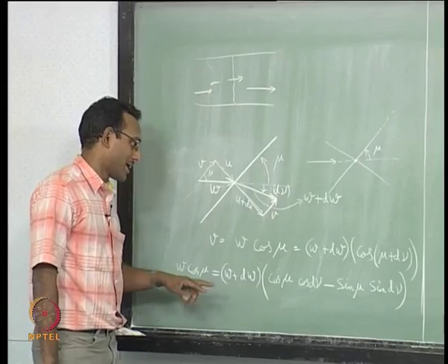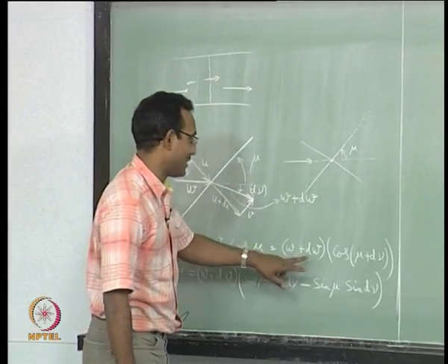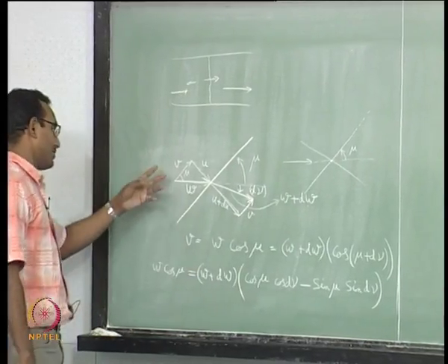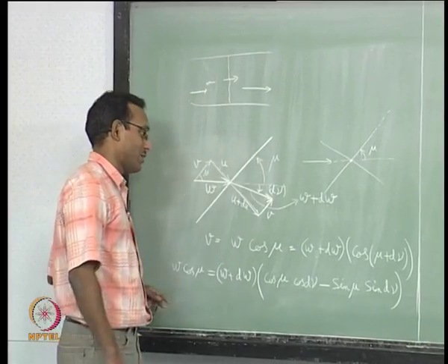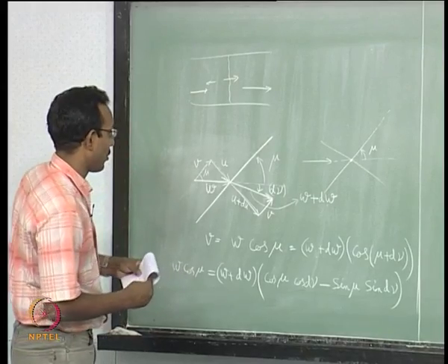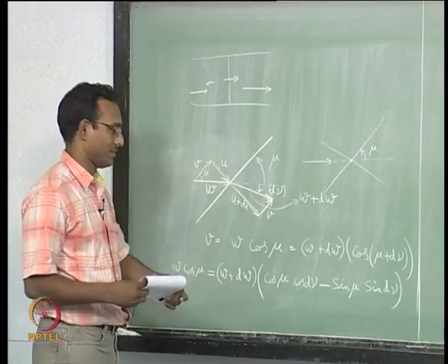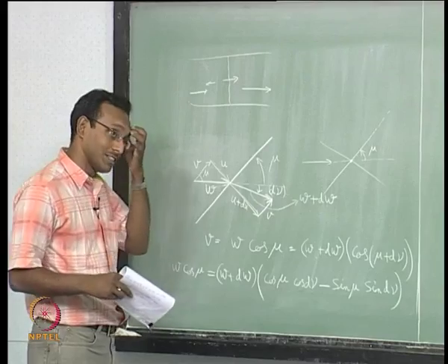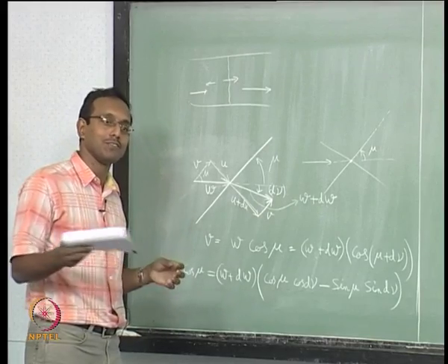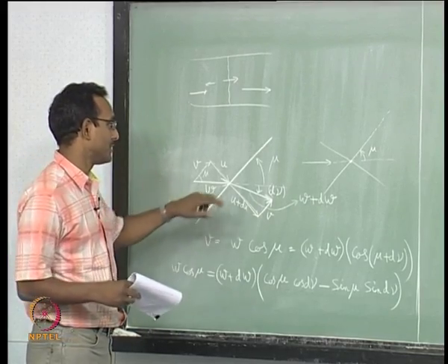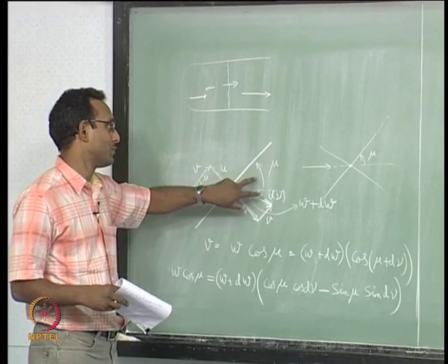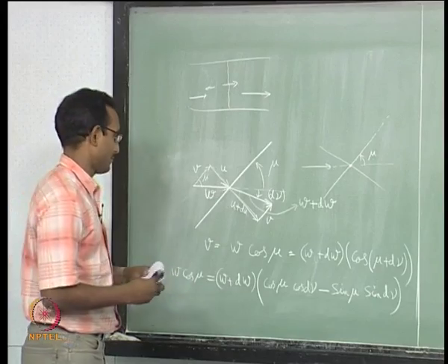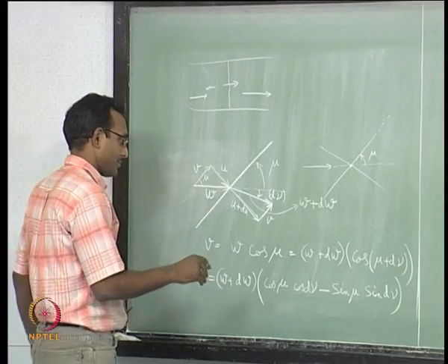I can now say that d nu is very small, dw is very small, du is very small, dp, dt, everything across this is very small, all of the order of d nu. Except for entropy, which I will force to be approximately 0, because we are using isentropic implicitly when I say mu is the angle here. We will keep it that way.